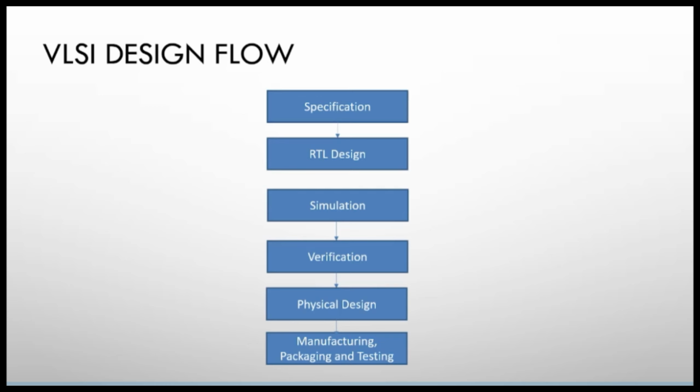In the same way, the verification engineer will send a group of data, not only one input but all the possible inputs. For all these possible inputs, your design should give the expected outputs. If your design is not giving the expected outputs, then the verification engineer will detect the bug, and it will be sent back to the RTL designer. Then the RTL designer will fix that bug, and it again undergoes simulation and then verification. This process continues until your RTL design code is bug free.